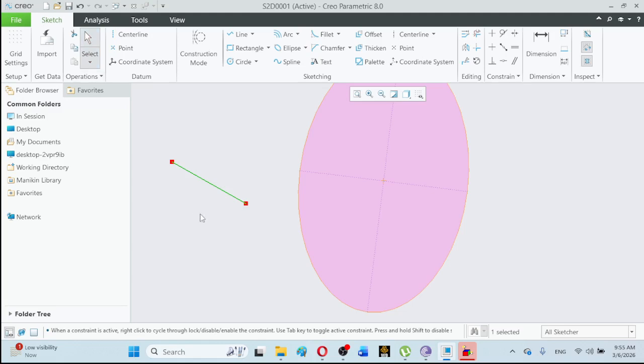So here, as we can observe, I can define the length of this line. For example, say it will be 15. This line is to be one of the axes of the ellipse, so its center point will be at 7.5 automatically. At 7.5 the center of the ellipse will be defined, and after that the distance between the center of